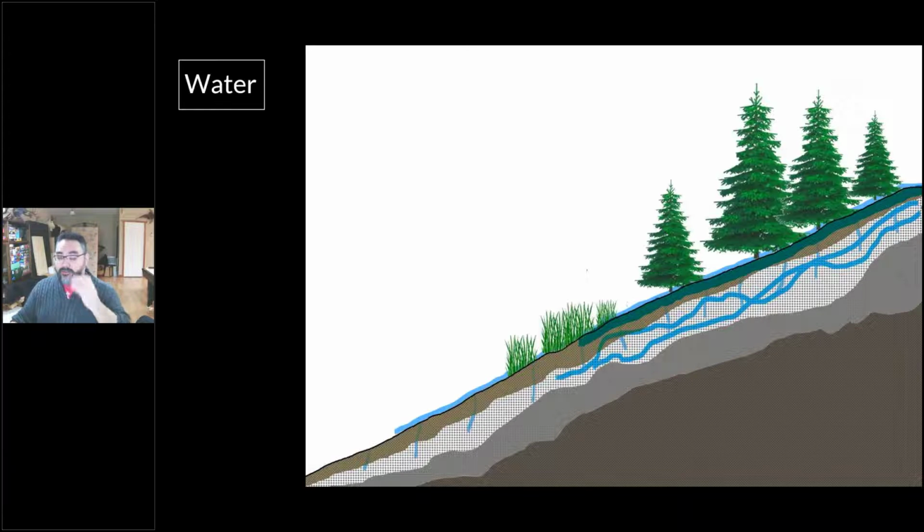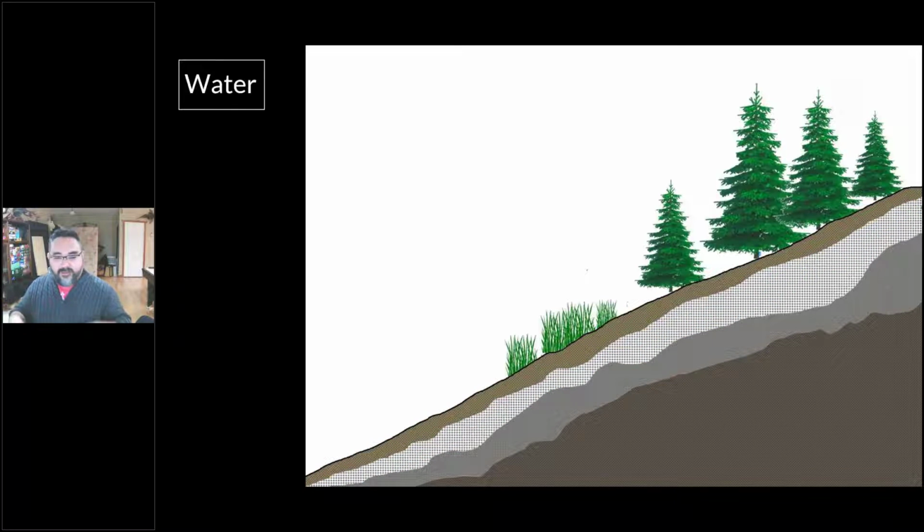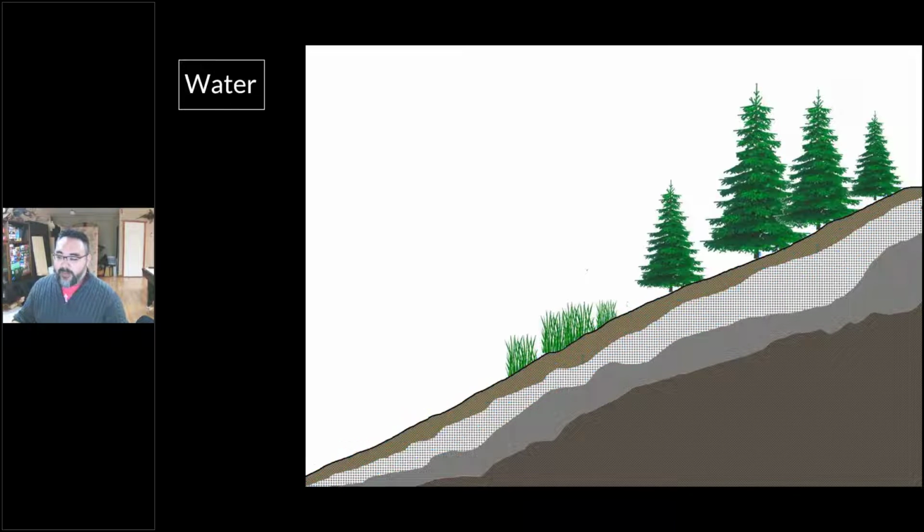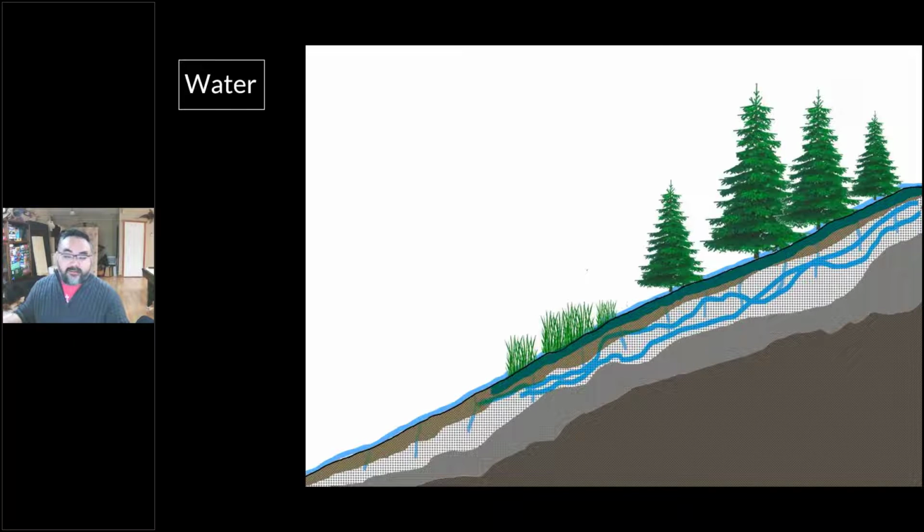But as it's flowing down the slope, it's also infiltrating. And that infiltration is really important because it slows the water down. We're not even talking about the uptake in the vegetation right now, just how it flows down the hill. As that water flows in, it slows down, and it can slow down orders of magnitude in velocity. So it's traveling through that slow soil profile. It's not only changing the speed, but it's changing how fast it's getting down the hill, because the path is not straight anymore.